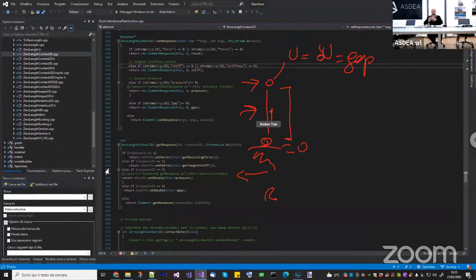But just because this is a very simple example. So monitoring the displacement at the top and the reaction at the base is actually equal to what's inside. Of course, the reaction changes sign. But that is actually a nodal response. So displacement on top versus the reactions times -1 at the bottom.